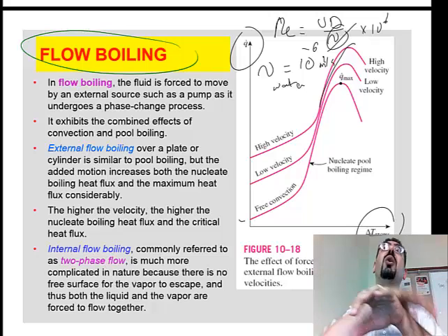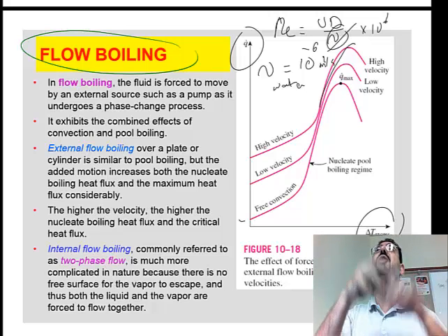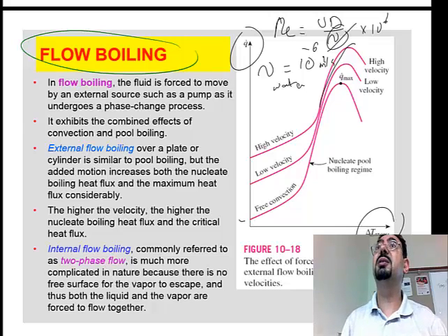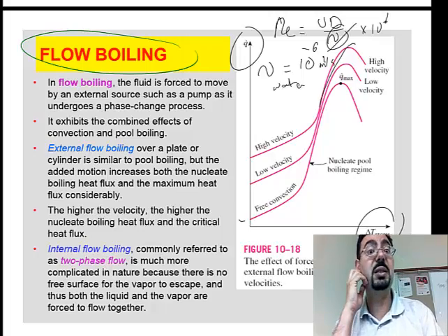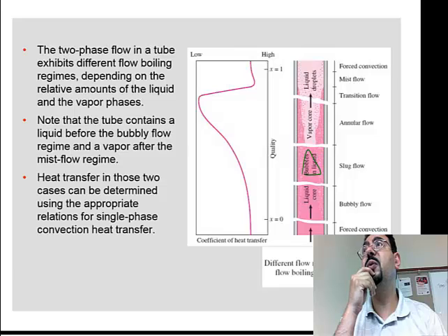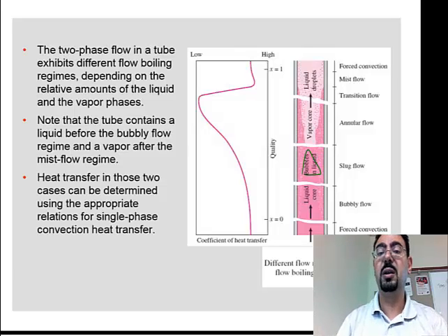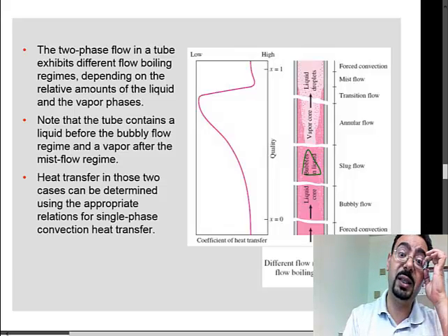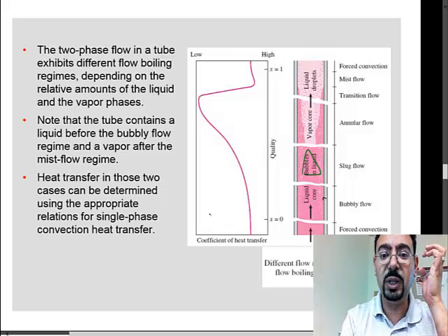If the flow is moving on a hot surface and the bubble wants to just sit there until it's big enough and get bigger, it immediately gets squished out of its way. It's basically removed very quickly. And when it's internal flow boiling like this, also you see improved heat transfer.